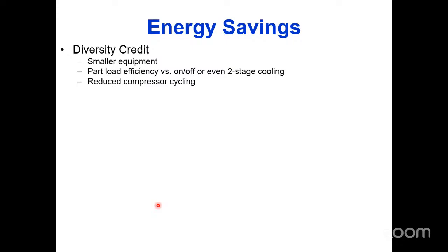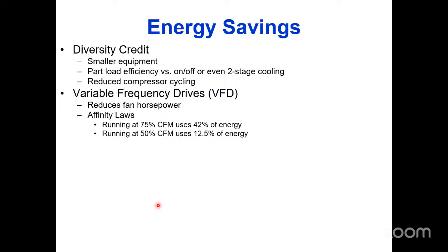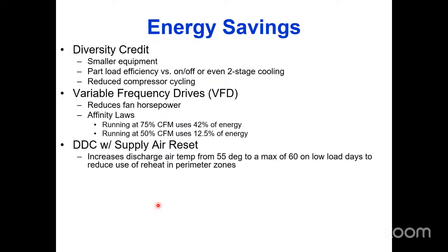I have to have some energy savings coming from all my part load control. Turning compressors off saves energy, right? So all that stuff's in my favor. The VFD, already mentioned, saves a bunch of energy. We can do what's called supply air reset. I already told you about that.